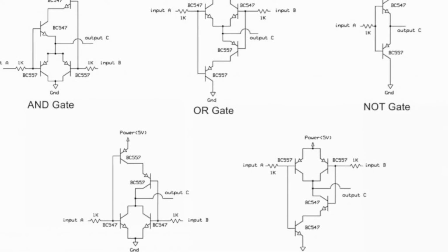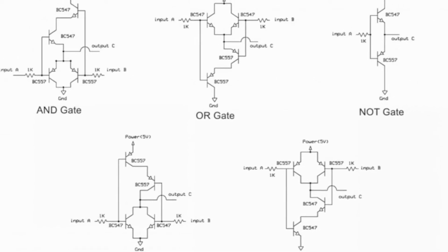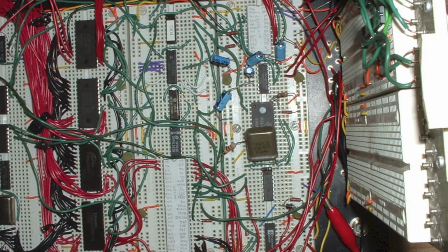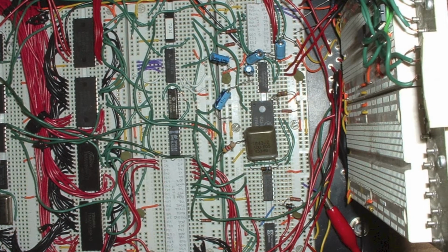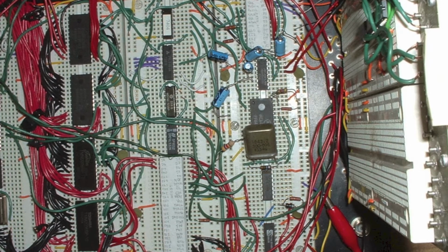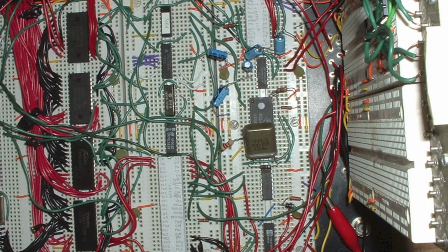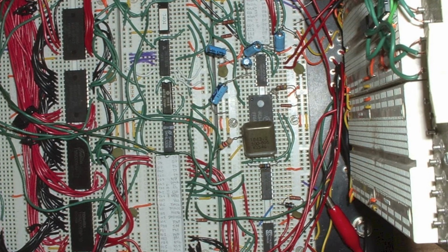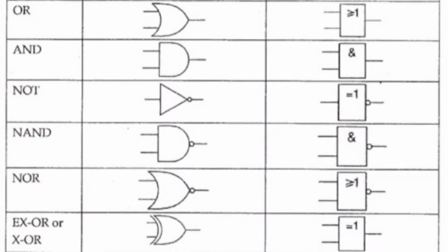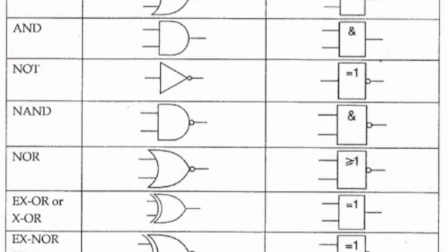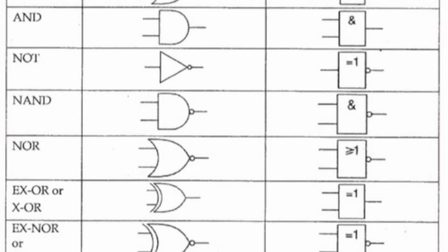Logic gates are primarily implemented using diodes or transistors acting as electronic switches. With amplification, logic gates can be cascaded in the same way that Boolean functions can be composed, allowing the construction of a physical model of all of Boolean logic, and therefore all of the algorithms and mathematics that can be described with Boolean logic. These gates are the AND, OR, NOT, NAND, NOR, XOR, and XNOR gates.